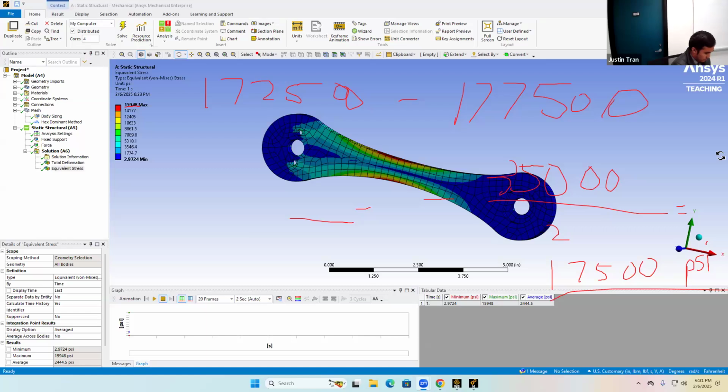So the second class, I was just listening to her and I was like, oh. And then we're only the last one. So cylindrical support's not necessary for this one. We're basically treating it as a pseudostatic simulation, so we're just applying the fixed support. Yeah, cylindrical support is more for dynamics, which we'll cover a little bit later on in the class, but dynamics are also a little bit hard.